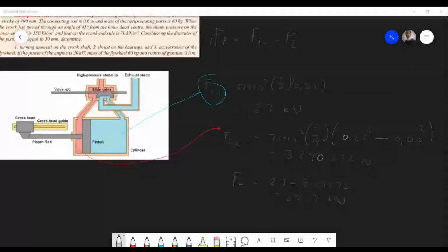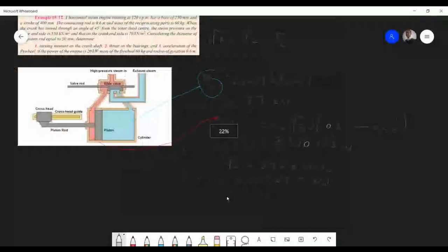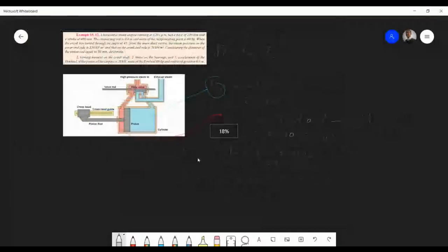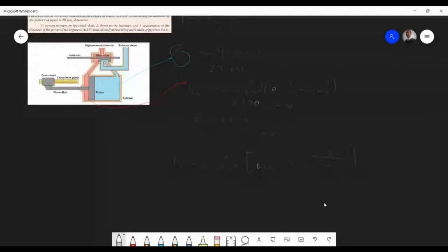Thank you. Again, guys, from here it's simple. All we have to do is work out our inertia force. Like I said, it's either one of these things you're always going to end up with: m omega squared r, probably doing it over and over. So there's no problems. You should absolutely get it. But obviously, I like the vertical more. Now I have to find n, and let's go.